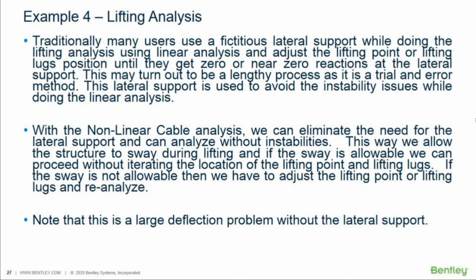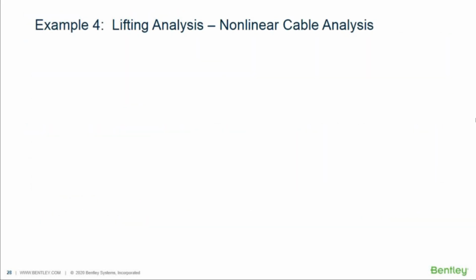Note that this is a large deflection problem without the lateral support. So when the center of gravity of the loading and the center of gravity of the geometry don't match, when you lift the platform, it will sway. That's why many users use some lateral support to avoid instability messages in the linear analysis. So let's quickly go through this video on lifting analysis.